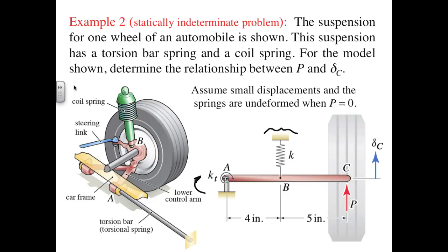Just as we were able to show in Chapter 3 that for this kind of element, we could write the spring constant as a product of cross-sectional area and elastic modulus, divided by length, we can use the geometry and material properties to come up with a similar torsional spring constant for such a torsional bar. For the idealized 2-dimensional model shown at lower right, we'd like to use our equations of static equilibrium